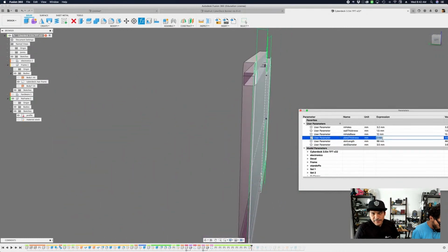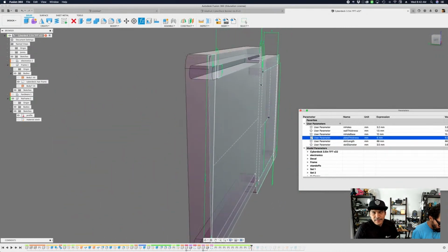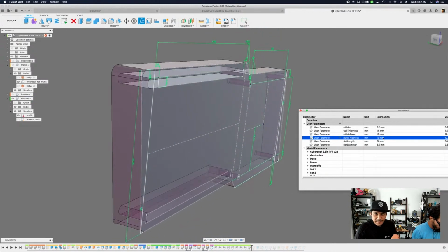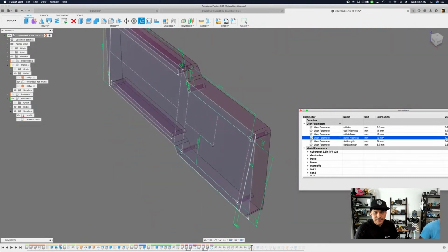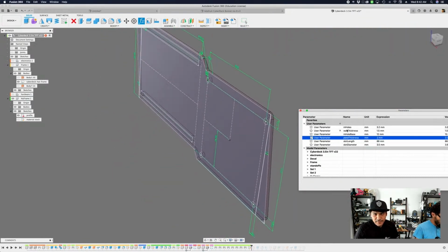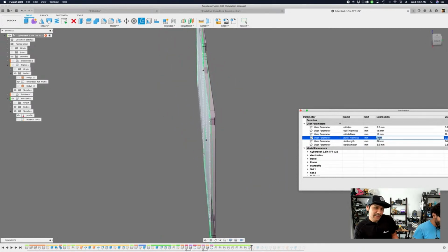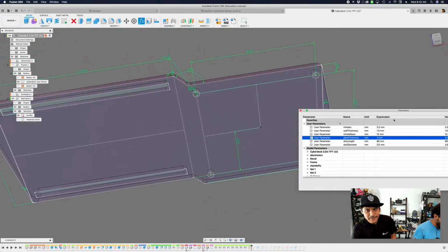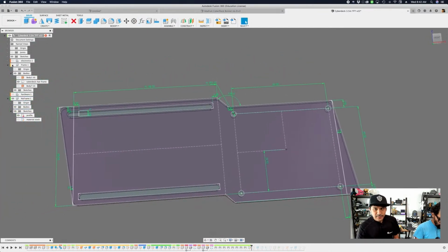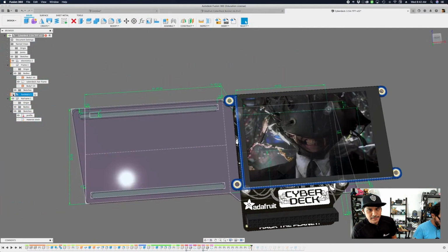You really want to pay attention to your material thickness because that will affect the amount of depth cuts that you need to make. So here I'm just changing it and showing that you can get pretty extreme on the thickness, or you can print it really thin if you'd like. It depends on what you're doing. But if you're milling and you're using the CAM tools, definitely take a look at this one.